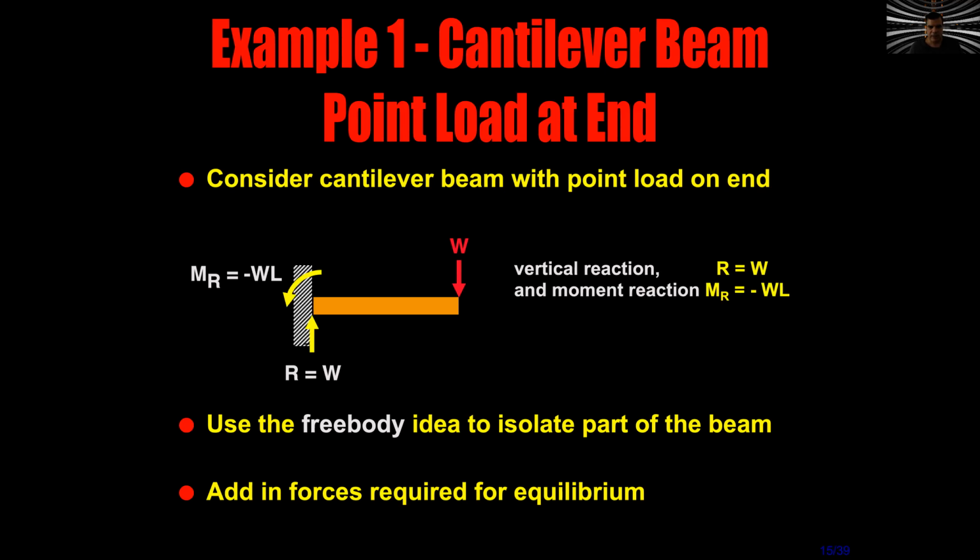Well, we have a vertical load called W in red color here that is acting on this yellow cantilever. When we cut, we imagine what happens in the corner. It's like the wall is not there anymore. What will happen? This force W will need another force that is contrary, in green color, that is also called W. Now the system is in equilibrium. Vertical forces are equal to vertical forces. W is equal to the reaction, that is W.